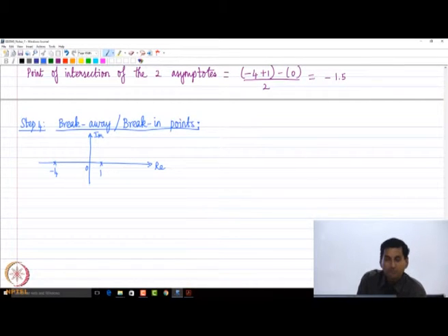These are two open loop poles on the real axis, without any open loop zero in between. And what did we discuss? As far as this example is concerned, I'm going to have one branch starting from minus 4 and coming to the right, one branch starting from plus 1 and coming to the left.